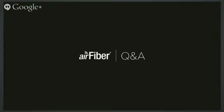what about performance in heavy rain or fog? What's the difference between 5 gig versus 24? Okay, there is a bit of difference there. The 24 gig spectrum is sensitive to high levels of humidity, which is rain. I don't know that fog really has much of an impact, but rain does. And so if you're in a particularly wet climate, and that's something that you find out by looking at maps that give an idea of how much rainfall you'd expect to see in a given year.